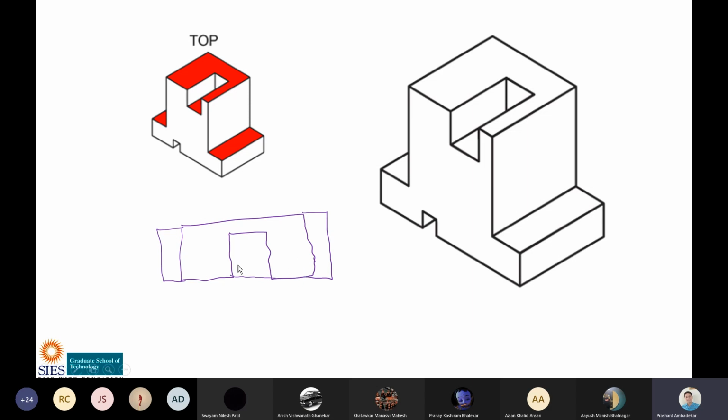Is it clear to all of you except the hidden part? I have not drawn that hidden part. Now I will explain how to draw hidden lines. Apart from hidden, I think this will be the top view. Now see this. This is there. How will it be seen? It will not be seen from above. So how will the operator come to know if this is a machining operation? Machining has to be done here, a threading operation is given, suppose, from below. So how will the operator understand?